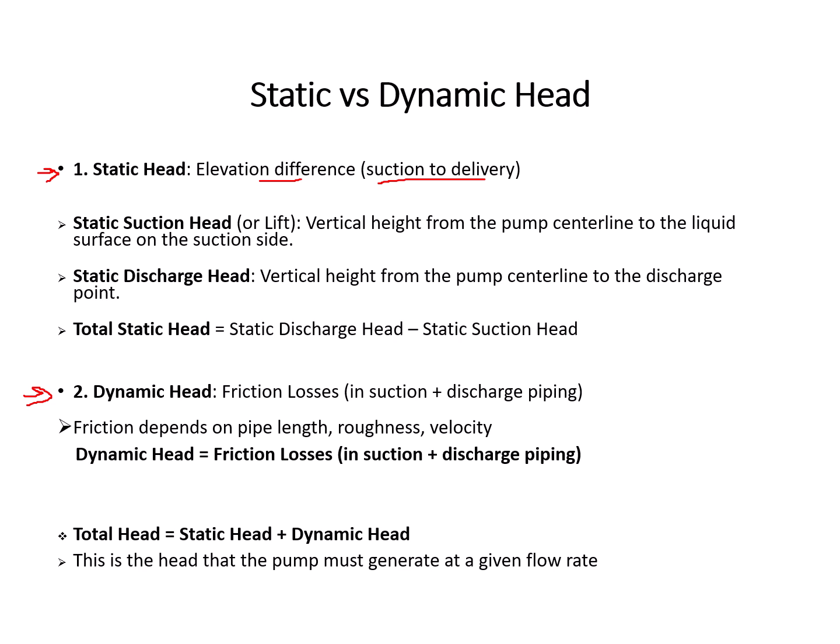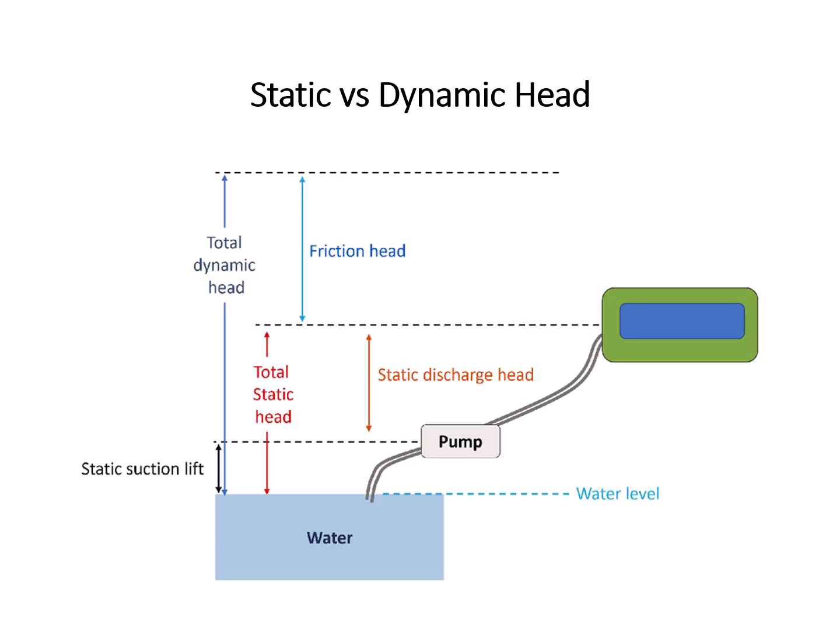Static suction head or lift is the vertical height from the pump center line to the liquid surface on the suction line. Okay, here it is. The static suction head is here, from the liquid surface to the center line of the pump. Okay.